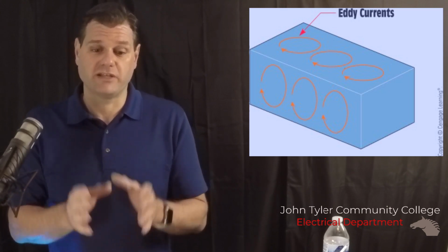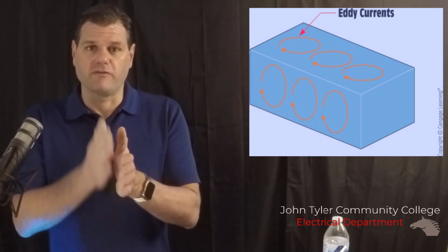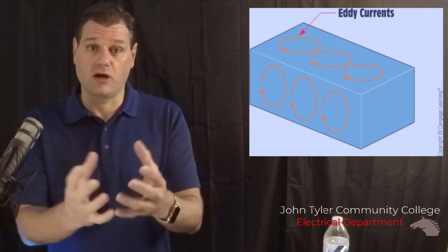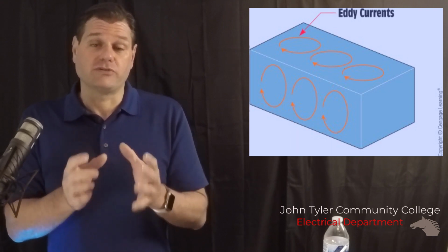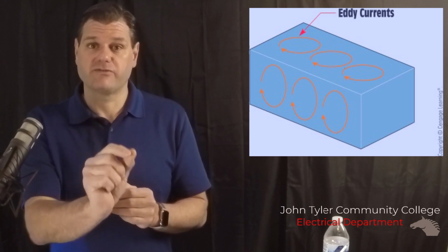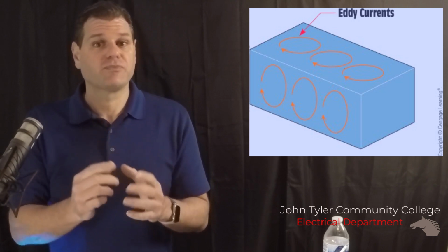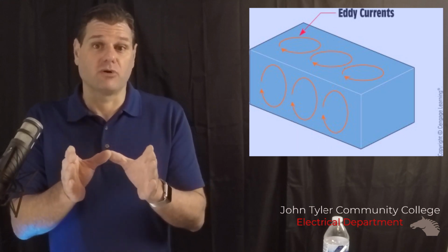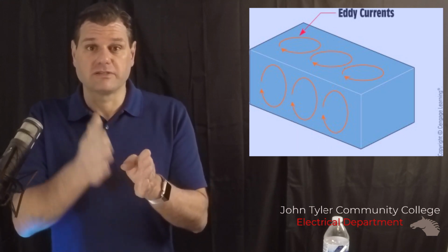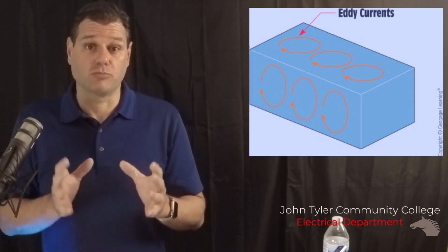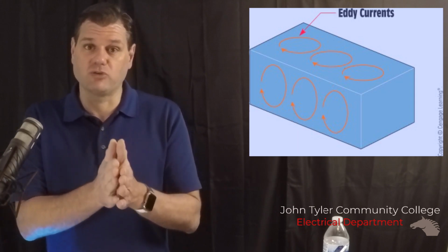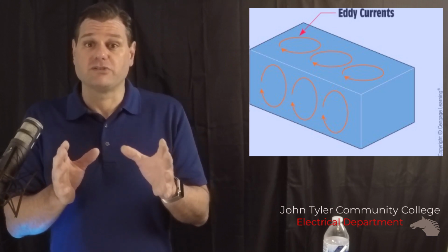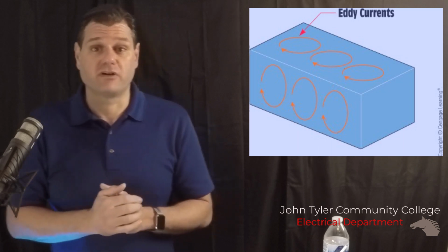Typically, instead of a giant piece of metal, a manufacturer will cut metal into very, very thin slices and laminate them together. This allows you to have your iron core, but it reduces the eddies, because with a thin slice of metal the eddies are very tiny, a lot less loss. So more efficient motors, if you look at them very carefully, are not a solid piece of metal. They are thin slices of a larger block, insulated between them and pushed together. That limits the eddy currents, but it is still a loss of energy we have.